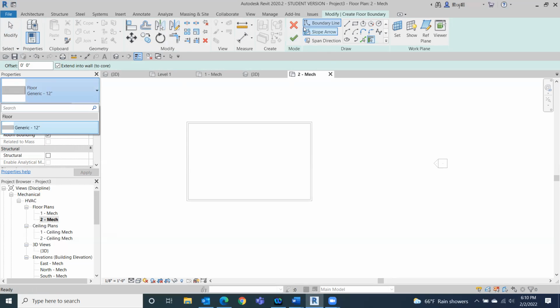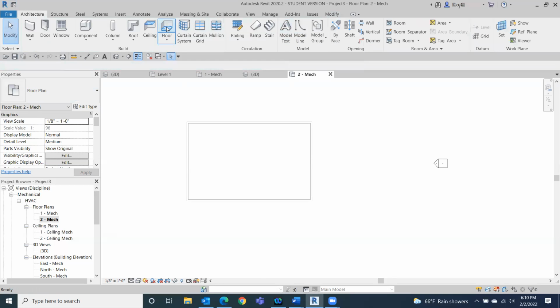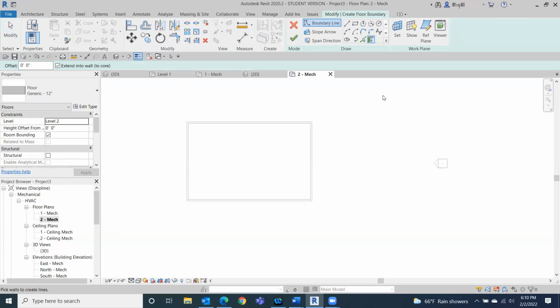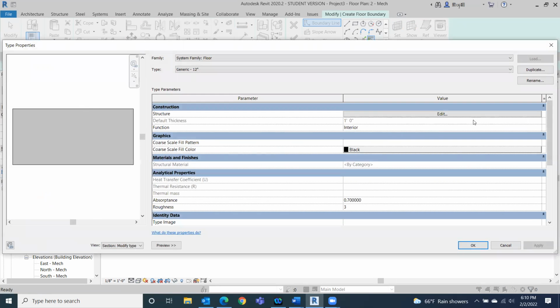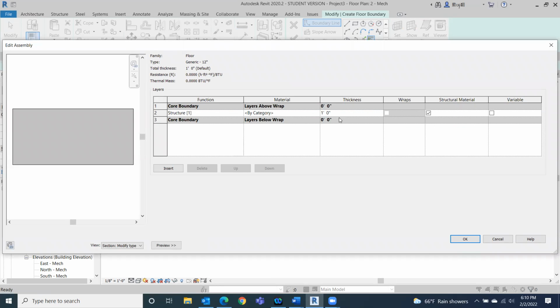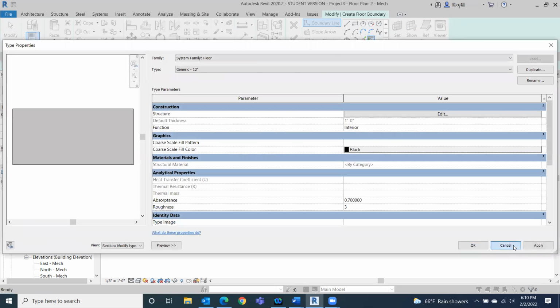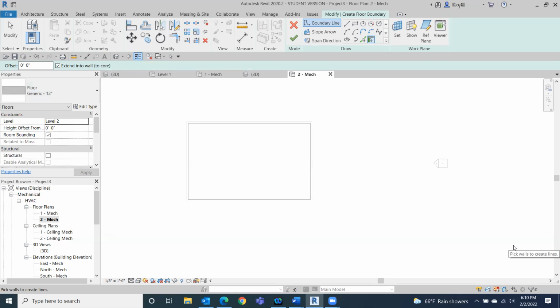Fun. Yeah, so that's exactly what it showed me. Oh, that's the only floor. I couldn't get into any other kind of flooring. Okay, so we'll drop that in. We'll just go into edit type there, edit, and we'll change the information here. What it was hoping that you could use is a structural floor that's a 3-inch corrugated concrete floor, but that's not really the thing that we're worried about.